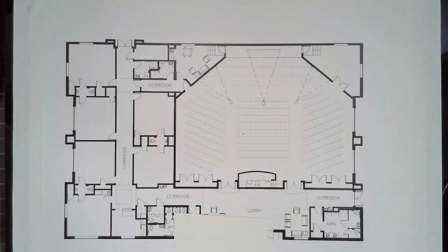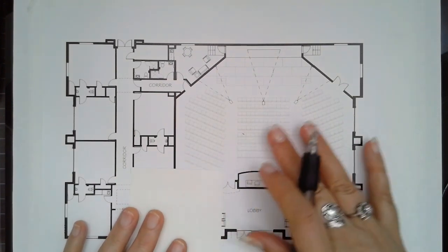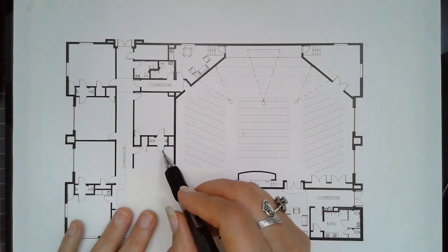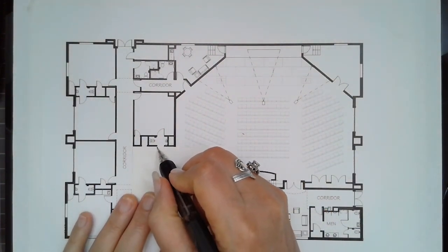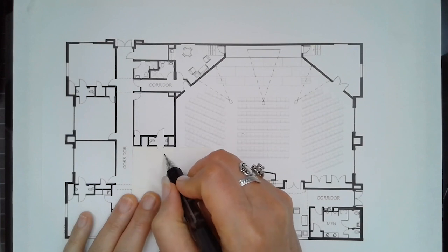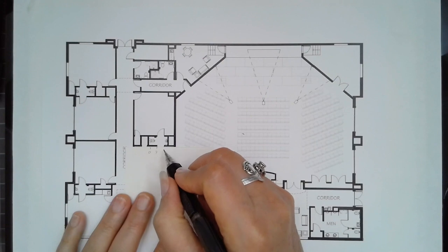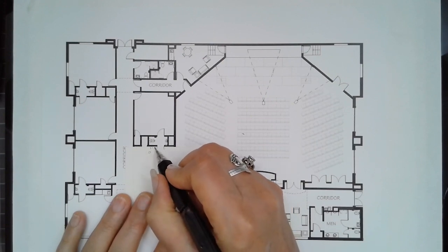So here we go. The first thing we need to do here in this drawing that I downloaded from the internet is establish a standard scale. It doesn't have a scale on it, so I'm going to pick a reference object. In this case, I'm going to use a doorway, which for accessibility reasons typically is going to be 3 feet in a public building. So I'm marking 3 feet here and then dividing that up into 1 foot segments. So I've got 2 3-foot segments.